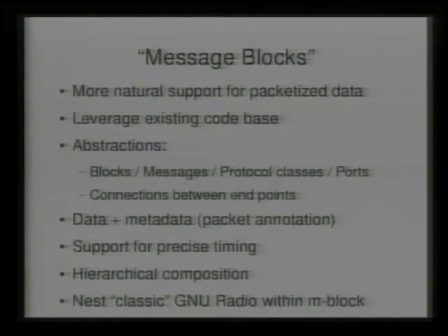And you say, hey, radio, can you transmit this using a particular modulation scheme or a particular amount of power? Or maybe there are annotations, like if you have a steerable antenna, please steer the antenna 100 microseconds prior to transmitting the packet. So we basically have these annotations on the side. Also support for really precise timing, which allows you to do time division multiple access waveforms, where you've got slotted things, or where you've got to do something and get a response back quickly. And it's all going to work with the classic GNU Radio all strung together.